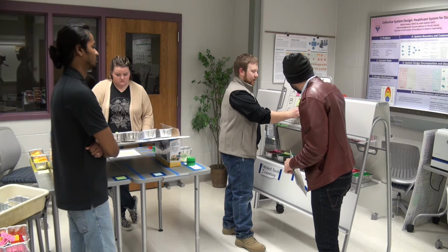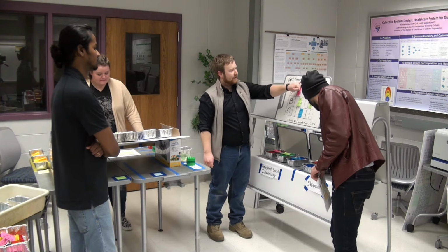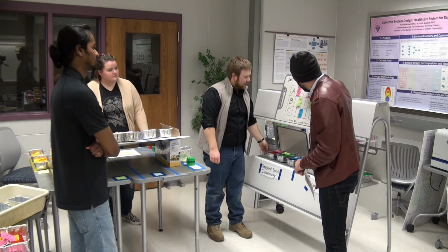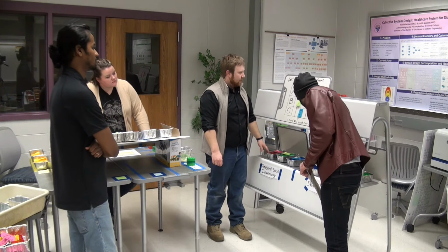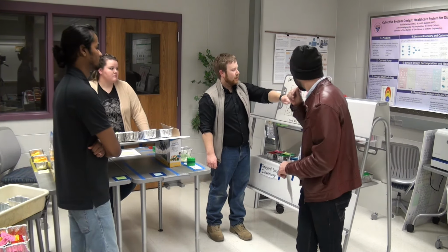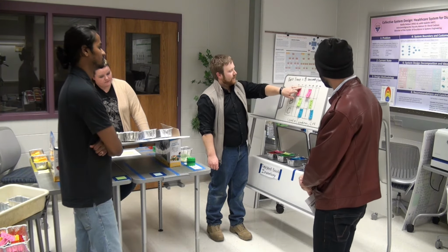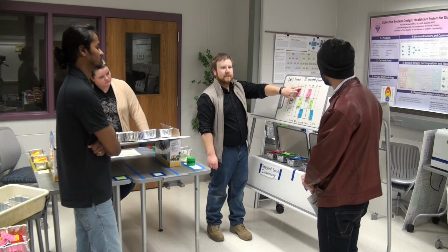If we look at the quantity, we've figured out our takt time, and we've used the container size to figure out our pitch. So our pitch being these 32, 64, 96, and so on. What it tells us is how often we have to produce a part to be successful.